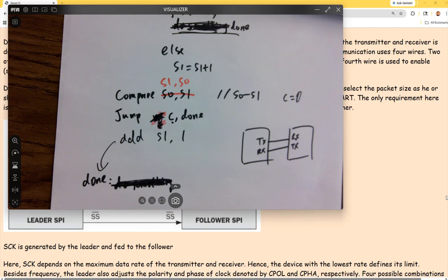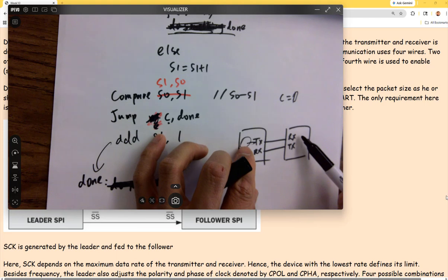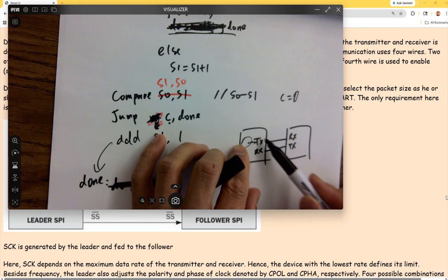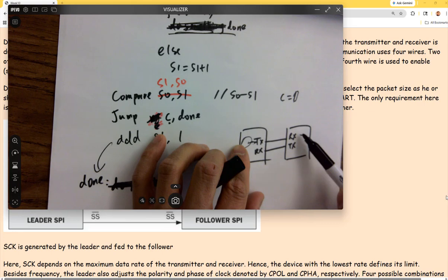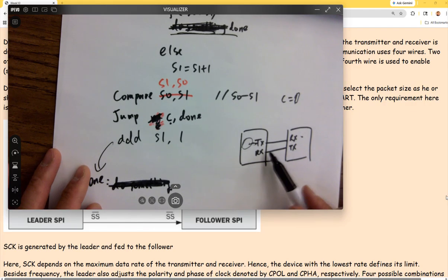So there's no clock for transmission and receiving, right? Is there just a clock internally sending data one by one, and they have agreement on the baud rate? So I'm pulling this up and down at a certain baud rate, and the receiver knows it, then just keeps taking data into the vectors, using the index to keep increasing the index to put it into the vector. The same for the other direction as well.